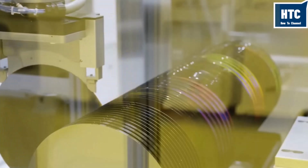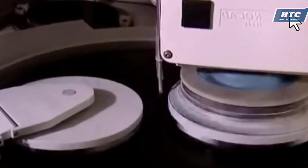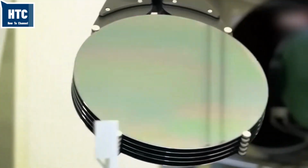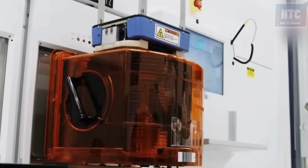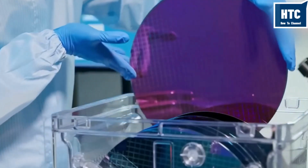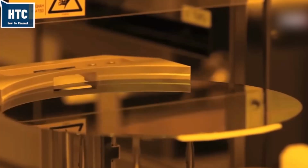Now we enter the front end of line, or FEOL. This is where the transistors are built. The wafer moves into the cleanroom, a Class 1 environment where the air is filtered continuously. The first step in patterning the chip is oxidation. We expose the wafer to oxygen in a high-heat furnace, growing a thin layer of silicon dioxide on the surface. This oxide acts as an electrical insulator, separating the future circuitry from the raw silicon base.